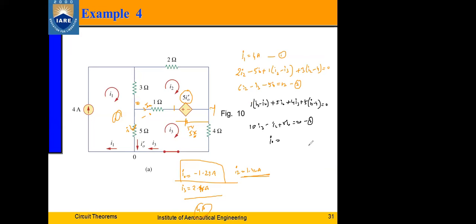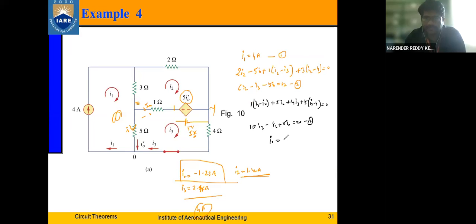Okay. So what is that I naught? I can replace it, since the direction we assumed was this. We already have that I1 is in the same direction, and I2, I3 we are assuming to be reversed. So I can write it as I1 minus I3. Will that be appropriate? I1 minus I3. It should be appropriate, right?